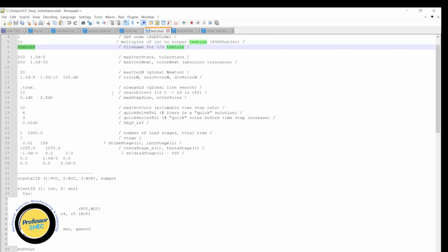You can just leave it for the time being. It's just about the iterations. It has to use maximum number of iterations for global Newton iteration as 20. You can increase it if you think you are not reaching convergence in your case. But these are default values. I never change them. They are pretty stable.